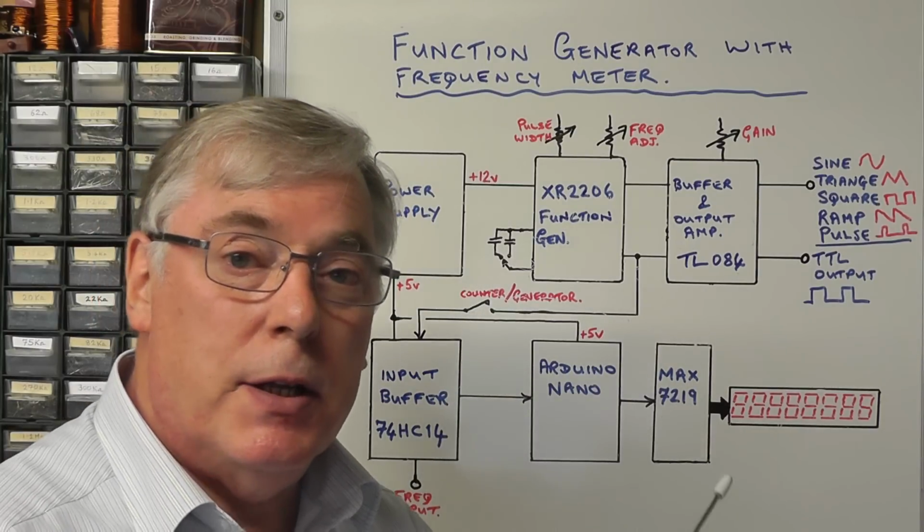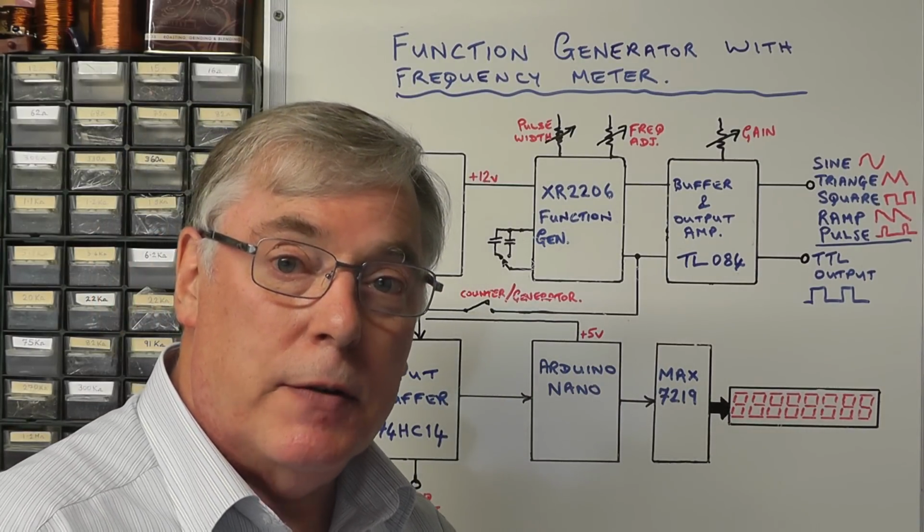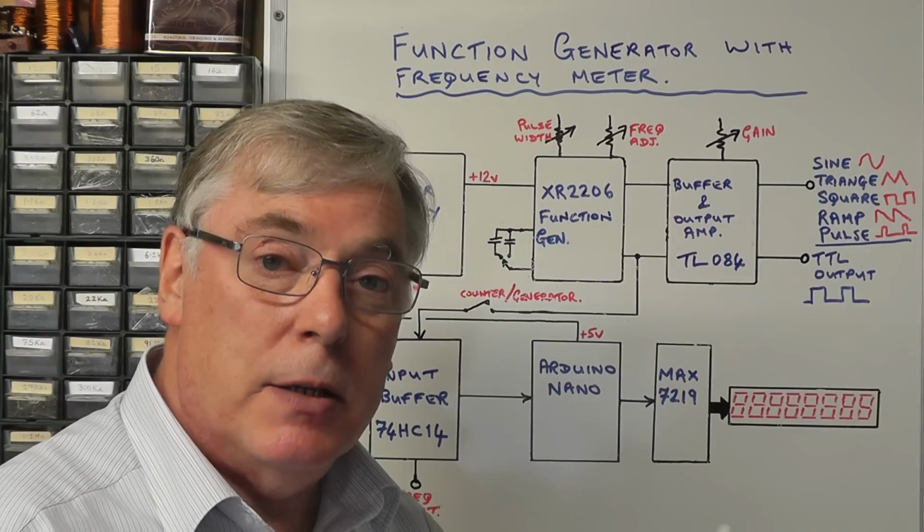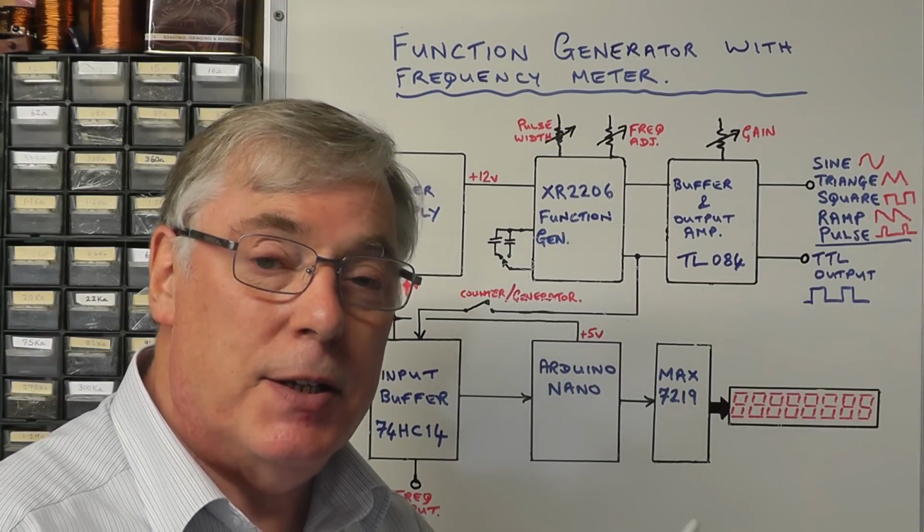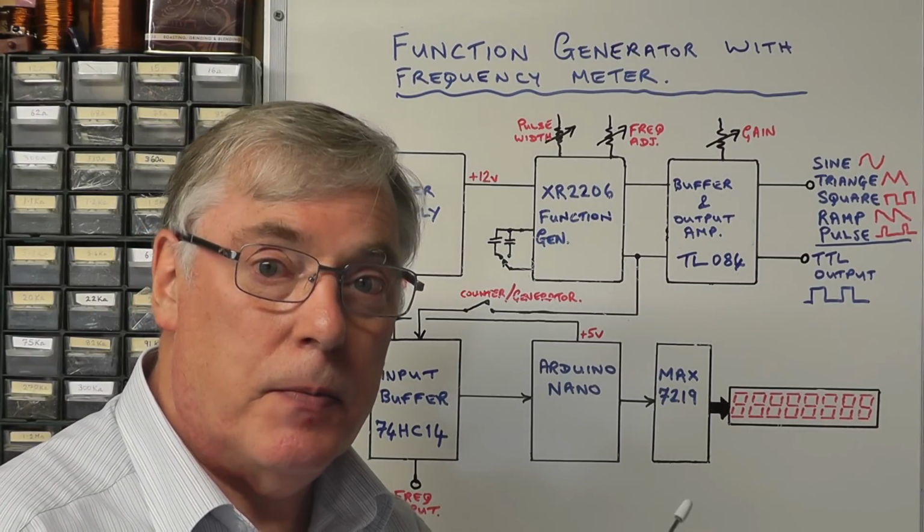The important thing there is that if you use one of these little transformer modules, then you need to ensure that you get one which says AC out, not DC, AC out.